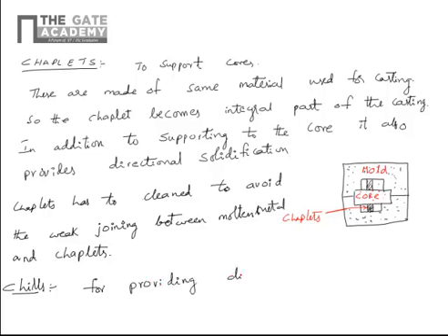Providing a metallic piece at the junction of an L shape or any cross sections increases heat transfer. So that's why these chills are used for increasing the heat transfer.